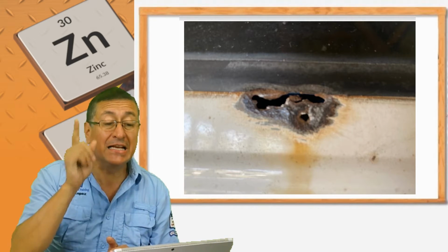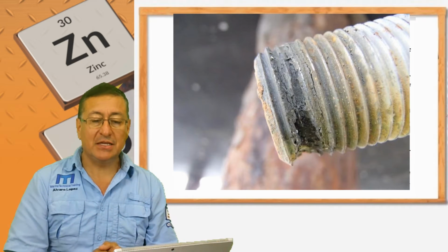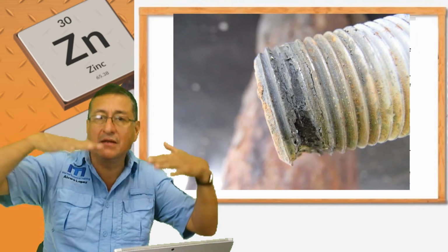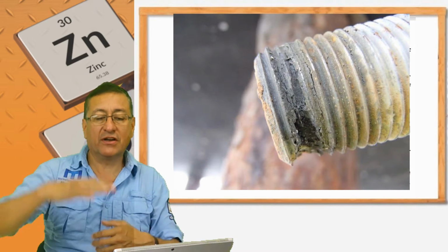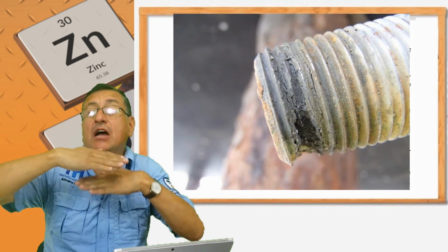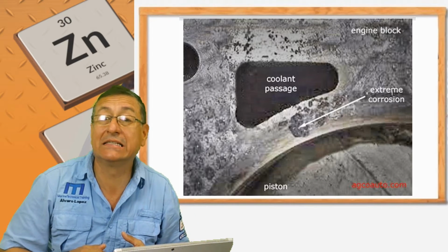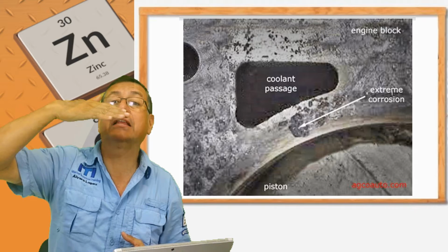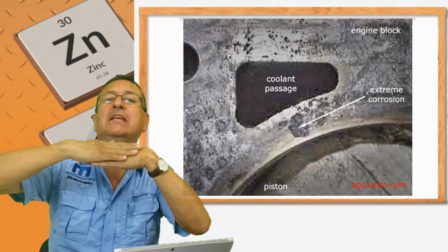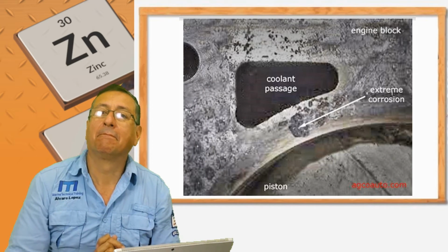Don't forget, clean. The second one, crevice corrosion. This type of corrosion is associated with stagnant environment solutions over the surface, or humidity accumulated in between two metals. For example, humidity in the head gasket, where you have an aluminum head with an iron block with humidity in between.